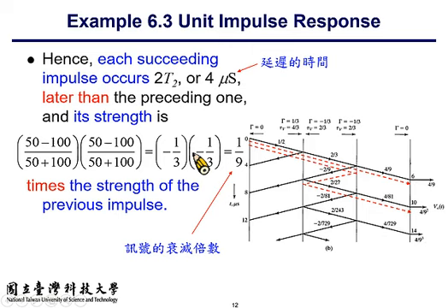The difference for the second part is this and this. There are -1 over 3 and -1 over 3 as over here. So the product of the 2 reflection coefficients is what? It is 1 over 9. So the magnitude of the second impulse shall equal 4 over 9 times 1 over 9.